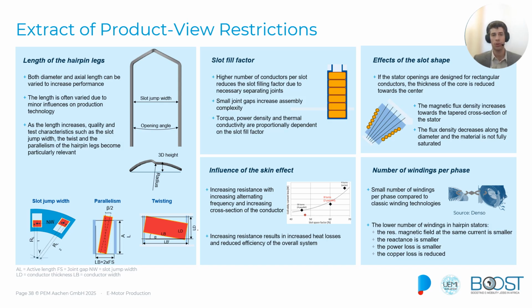We want to achieve a high slot fill factor with this technology, but a high slot fill factor can lead to restrictions like increased difficulty in inserting hairpins, potential overheating due to limited cooling space, and challenges in ensuring uniform insulation and electrical performance.